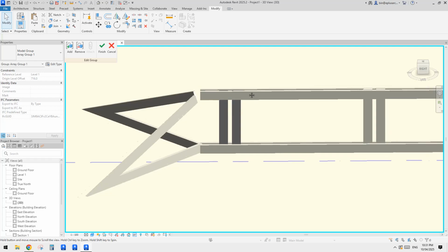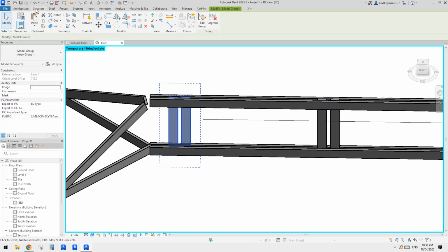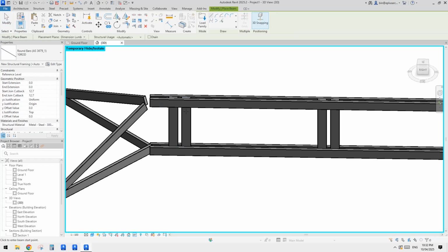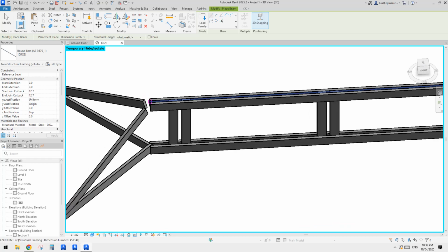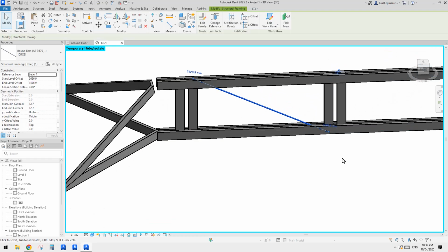So which means when we try to place a bracing, when you try to use 3D snapping, top SE snap endpoint, see, we can pick the middle point. So let's just, oh hell, what's going on here? Yeah, and then it's a bit hard to pick that point. So let's type SE snap endpoint, tab, click.